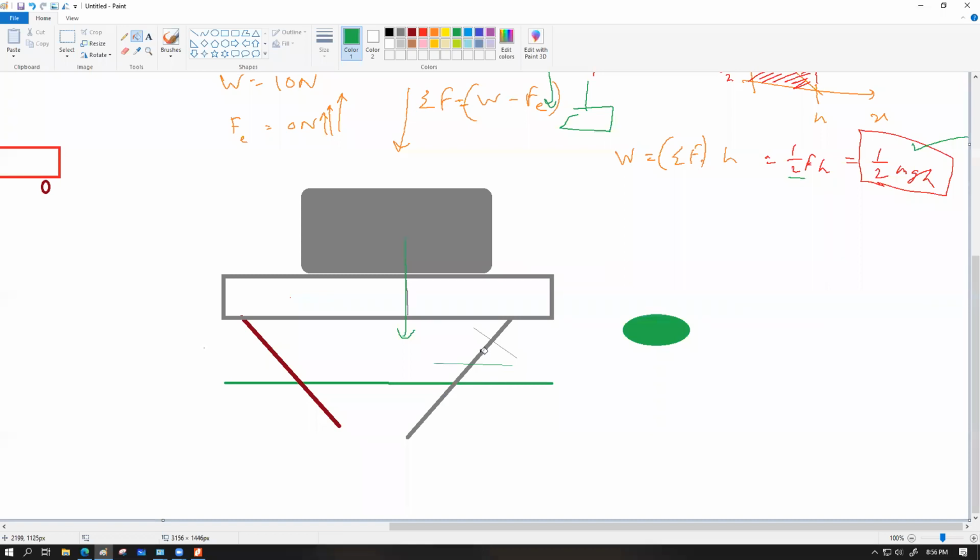Shear stress means this rod is going to undergo a type of stress for which it is going to try to separate out from one layer to another layer. Assume that this thing is made up of coins, and there exists a very strong force between the coins which makes it work as a cylinder. Let's say at one point if one coin starts to slide off another coin, the type of stress that you would have to build up is called a shear stress. So here shear stress will be there, and also linear stress along the axis of the object. Both will be there.